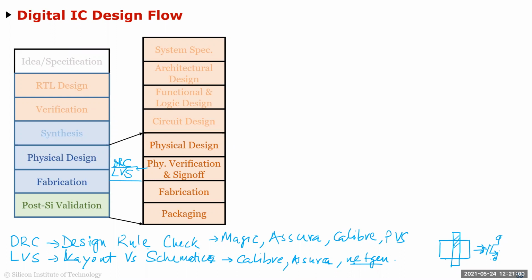So for example, this custom verification process here, it doesn't matter if you're doing custom or fully automated. Let's say, for example, you're doing SPI, right? Your verification is to make sure that you match the timing diagram of the protocol, right? The timing diagram which I showed you on the first slide. Now, if you use an automated process, then the circuit is synthesized automatically, but you still have to verify and make sure that it is meeting all the specs.